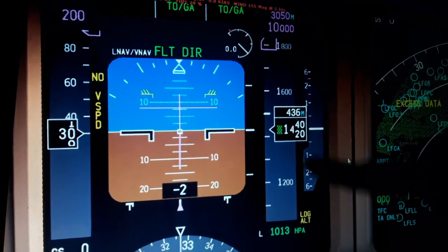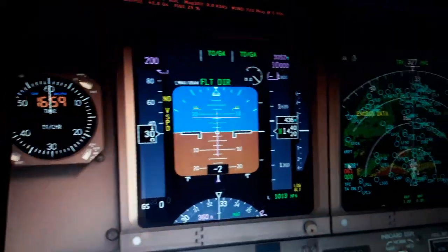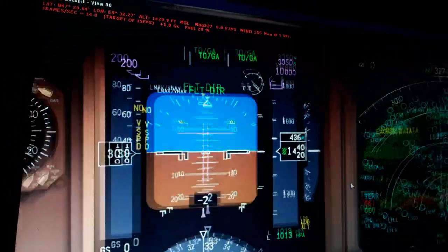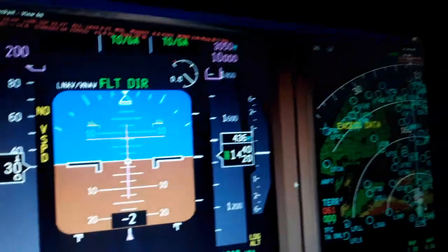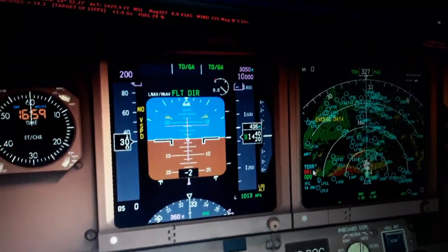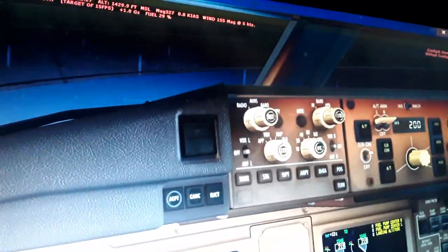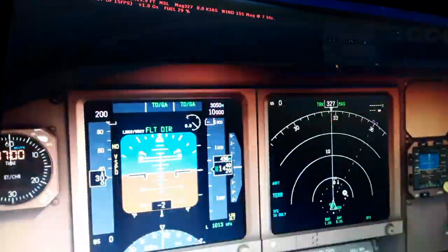So you have to look at this indication to see whether the aircraft climbs or descends in flight. So you have also the airspeed and flight mode and the angle of attack of the aircraft, the flight director. We can see here also the indications, the weather radar and the terrain reflections, as I told you. The elevation of the terrain, green, red and yellow and blue.